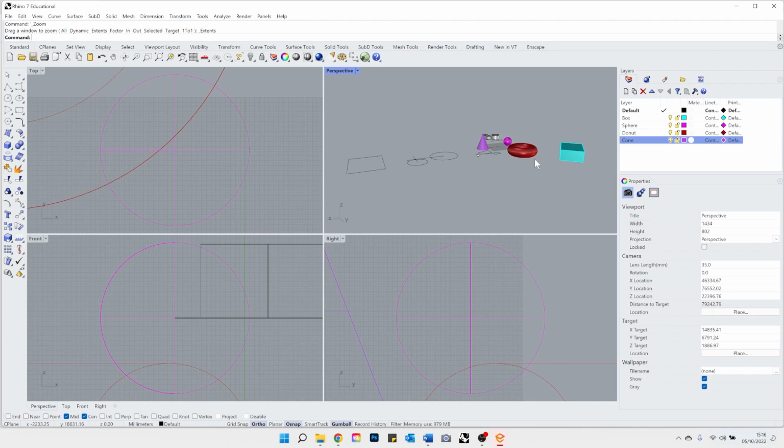So if you open your model in Rhino and you can straight away see where it's located, you can, for example, move it to the 0 coordinates, so you can straight away find it in any different package. If you do it in rendering, it's going to straight away open in the middle, or you just get the idea where it's located. Yes, I can quickly show you how it's done.